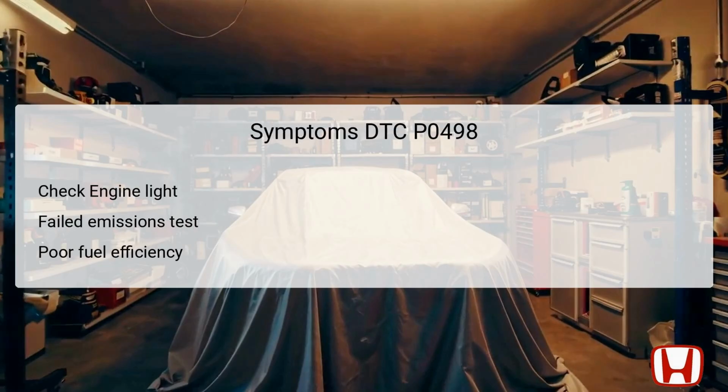When DTC P0498 is triggered, there are several symptoms that drivers may experience. The check engine light on the dashboard typically activates, indicating that there is an issue within the vehicle's emission system. Another sign of trouble may be a failed emissions test during routine inspections, as the EVAP system is closely monitored